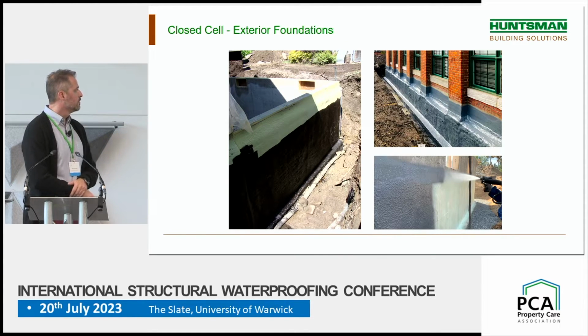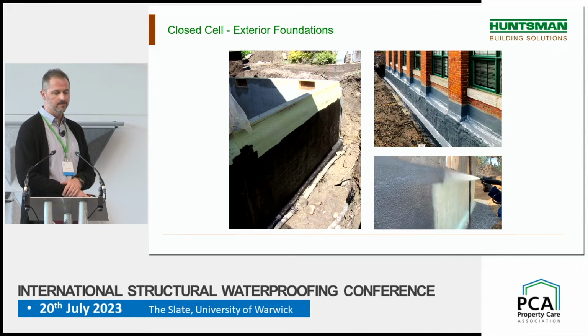So still, exterior foundation, as I was saying, closed cell spray foam is not a waterproofing product. If you want to get a full waterproofing system, you need to apply a waterproofing membrane on top of the foam. It could be a polyurea system that we manufacture as well. These are the two images on the right. If not, it could be a bituminous product or a spray applied membrane. Spray foam is compatible with bituminous products, as opposed to board stock insulation, which will melt when in contact with bituminous products.